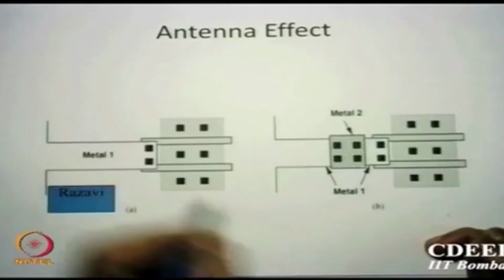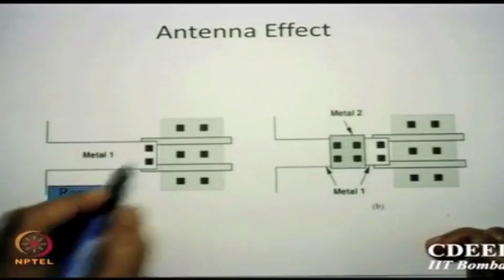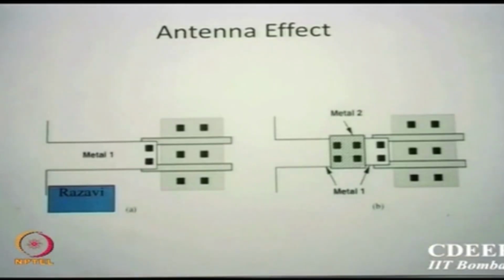So now, this is a similar transistor shown here. One method was that you connect the common gate together and put one big metal. There is a suggestion that if you have a single metal layer connecting to the contacts here and you run it longer as we did here, it gives some kind of resonator circuit on an oxide.